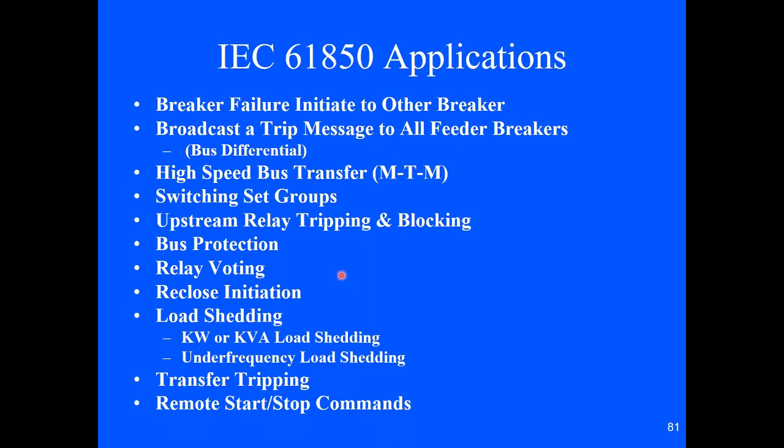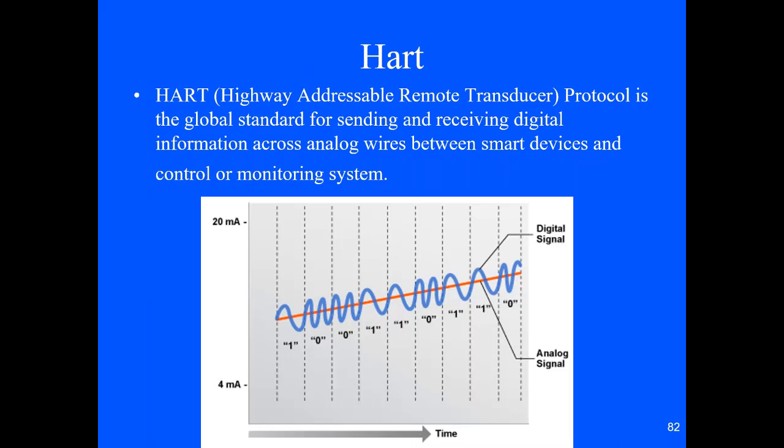Different applications, I can use it for a main-tie-main. Instead of using 14 wires going between all the devices, I just connect 1 fiber and I'm done. It's actually more reliable than putting in wires because within 2 milliseconds, I'll know if something's failed. I can do load shedding schemes, voting protection, transfer trip bus, a lot of great applications of it.